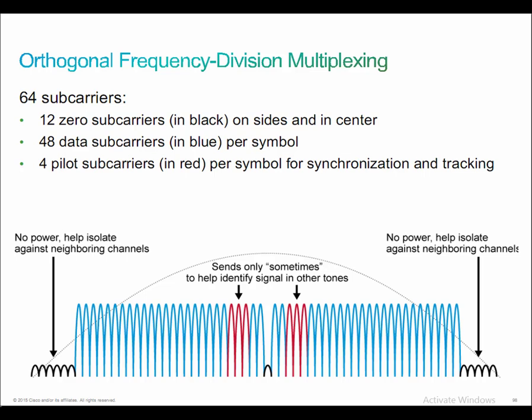So this modulation technique that was found was OFDM. Like I said, OFDM was already being used in radio transmissions, and it offered almost a perfect play to replace DSSS for our Wi-Fi networks. But the frequency spectrum is divided up significantly differently than when we dealt with DSSS or even FHSS. Instead of using one large 22 megahertz wide channel, OFDM actually divides the carrier into 64 subcarriers, and that's what you see depicted here on the diagram.